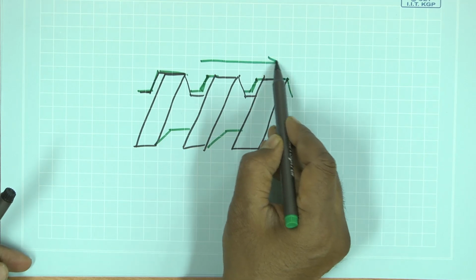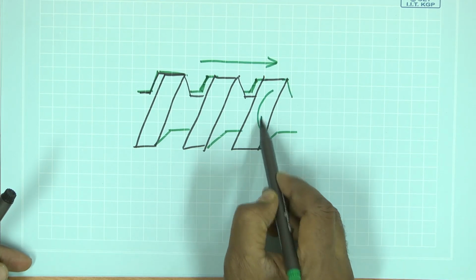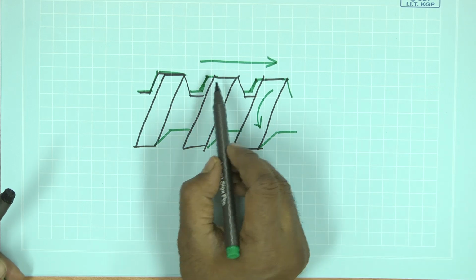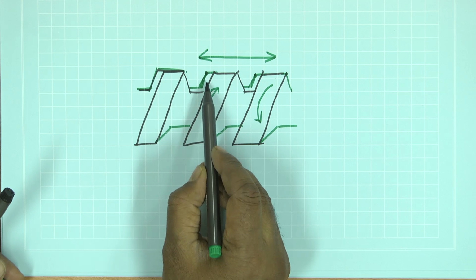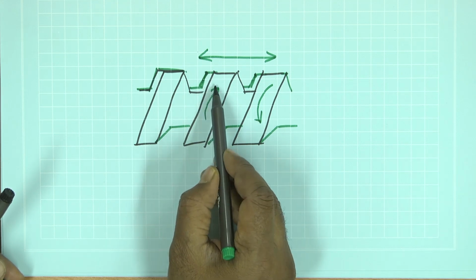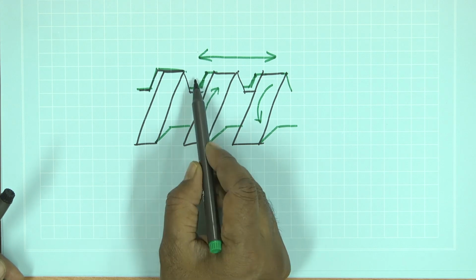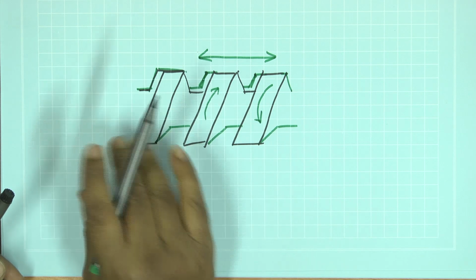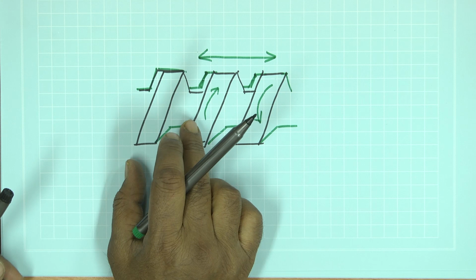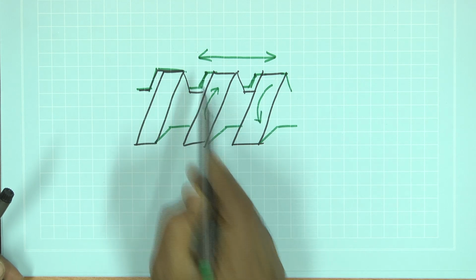So, first the nut is moving this way due to rotation of the screw, and next the screw is rotating in the other direction and pushing the nut this way, and due to this gap it has to first cross this gap and get in touch with this nut. So, in screws also we are now establishing that there is this backlash due to the clearance.